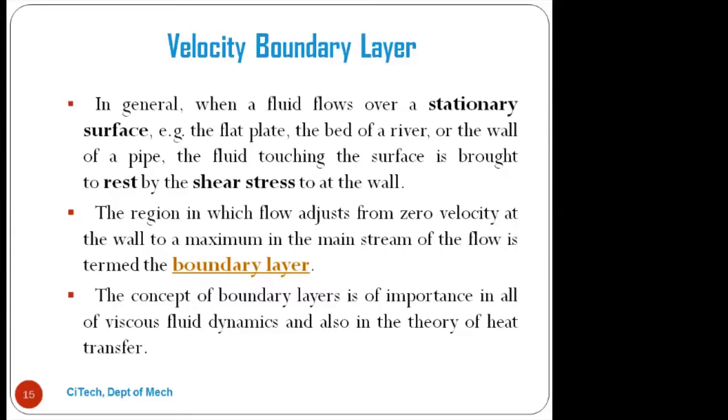In forced convection the velocity is very important, because if the velocity increases, the heat transfer rate also increases. Hence we need to discuss the concept of the velocity boundary layer, which is very important in forced convection.